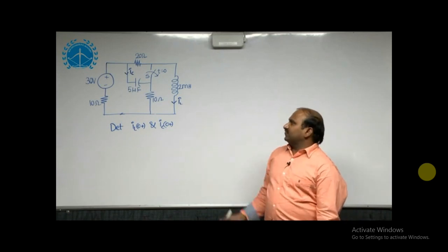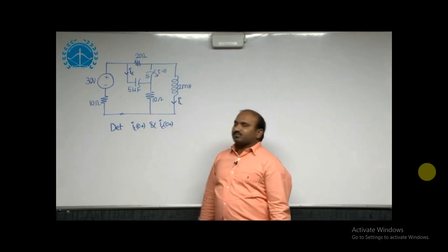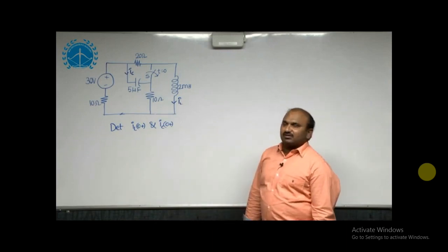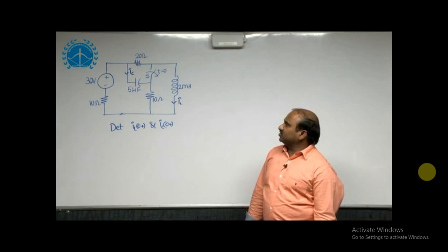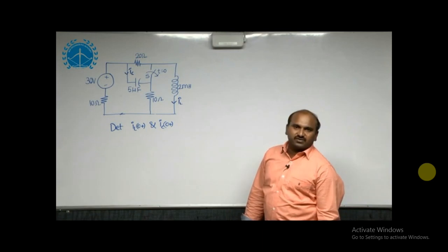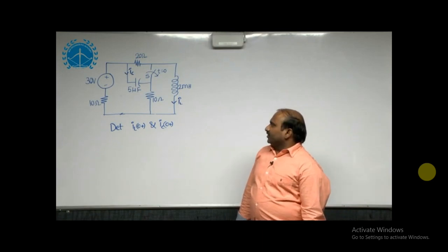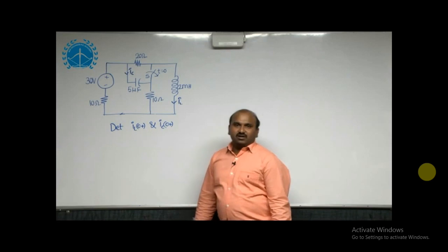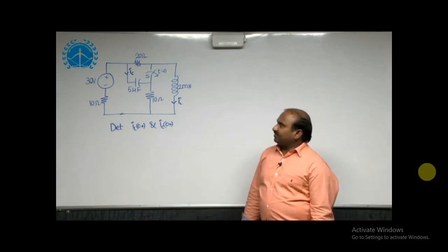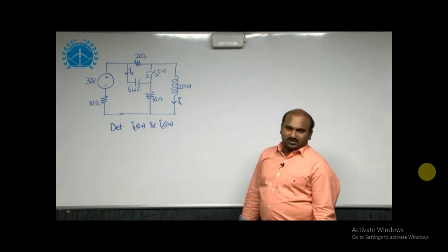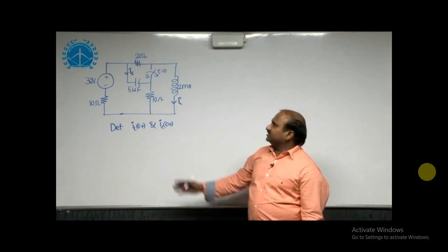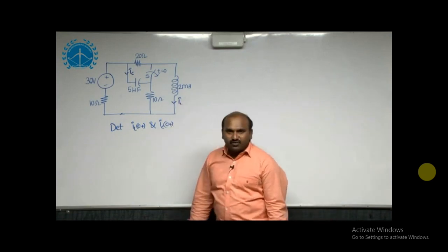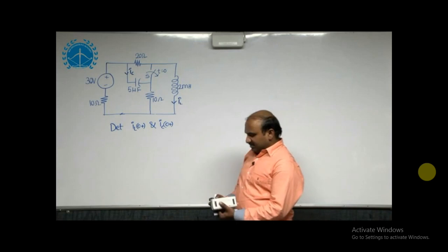Now, in this network, inductor and capacitors are provided. That's why we are getting transient responses after t equal to 0, because sudden changes are provided with the effect of the switch. Now, we need to check whether the initial voltage and currents exist in the capacitor and inductor or not. We will get the initial values by considering the switching action before t equal to 0.